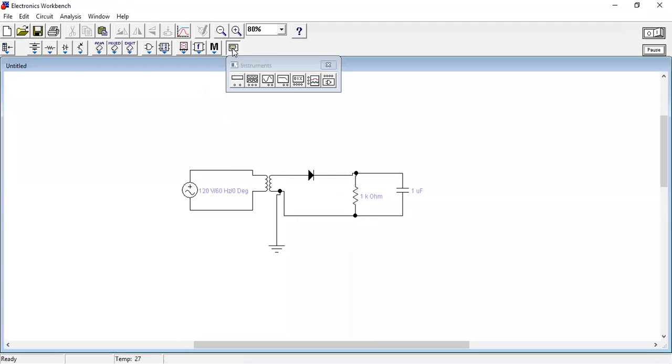And we can put in the values for the AC source and everything. To put the value, we right click the AC source, there is component properties, and we can change the value here to 12 volts, and we can change the frequency as you wish.